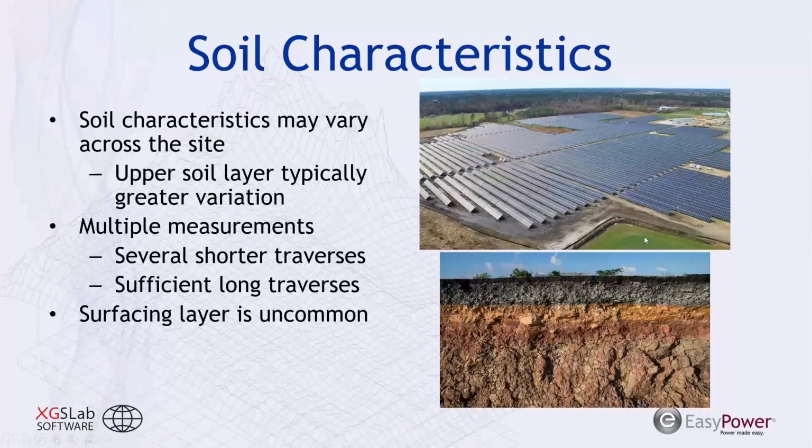But those top layers are going to see human interaction and more recent climate events that are going to change how that soil resistivity looks. So multiple measurements is a typical process in characterizing that upper soil resistivity values and seeing how it might change across the site.